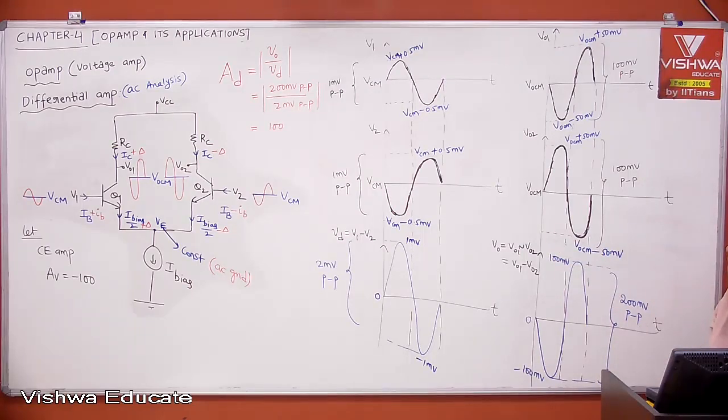Then we can go for different practical differential amplifiers. Then we will calculate the common mode gain for that. But remember, for a practical differential amplifier also, your AC gain won't change. Whatever we got now, the same thing we will get. Only the common mode gain will change. That part we will design, and then I can say the op amp block diagram explanation is over.